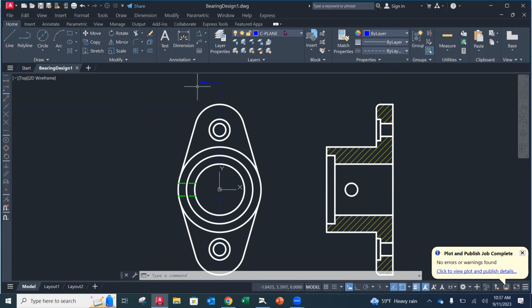We're going to go to our center layer, and all we're going to do is find those centers, right? We're going to hover over them, get in alignment with them, and go just outside the circle, and it doesn't have to be perfect. I need to put my ortho back on. Doesn't have to be perfect, and just outside the other side. Escape.